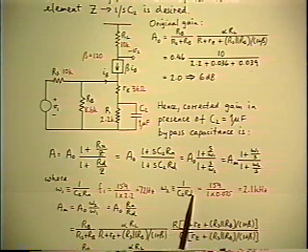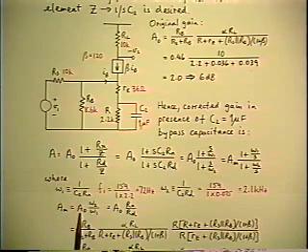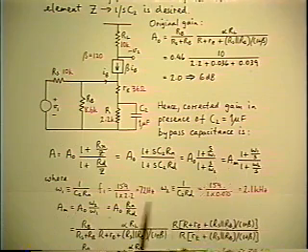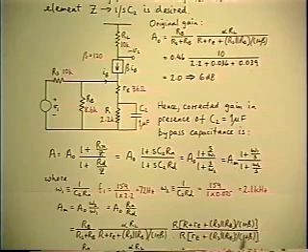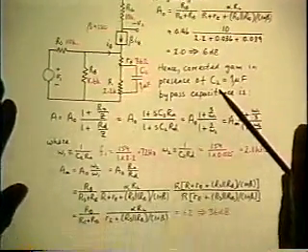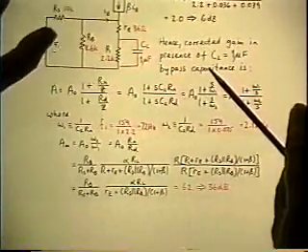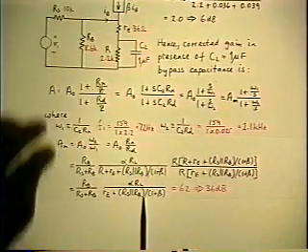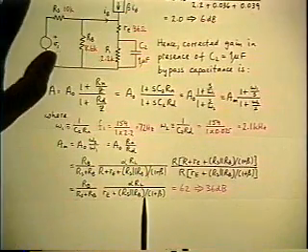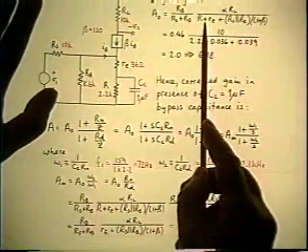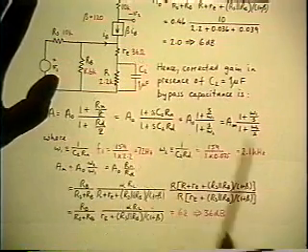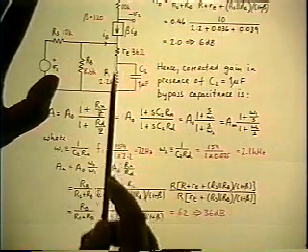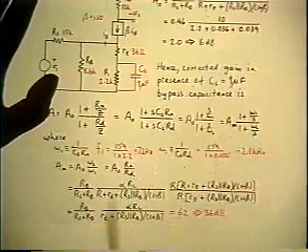And from the definitions we have here, you can verify that the gain bandwidth trade-off works, because AM can be found from A0 times the ratio of the corner frequencies, and when you make that substitution, it comes out to this result, which, as you would expect, is the same as the A0, except that the R has vanished, which is what happens, of course, at the high frequency limit when the C2 bypasses the R out of the picture.